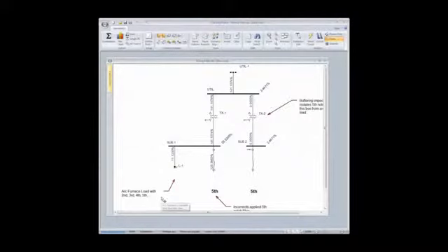This is not very much in line with our 6-pulse characteristic harmonics of a drive, where the fifth is going to be negative sequence, and the 7th will be positive sequence. What happens is you'll have thirds appear that happen to be positive and negative, and so they'll just blow right through transformers, and you're going to have to deal with them. So in this case, a fifth harmonic filter was a poor application, bringing the point home.